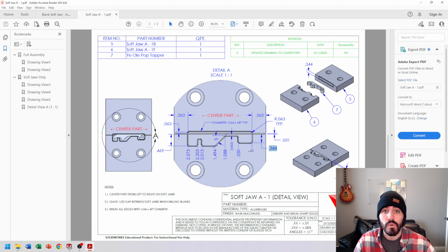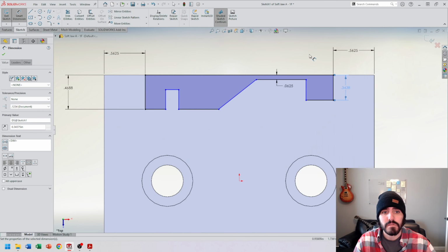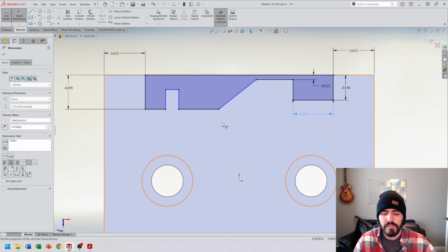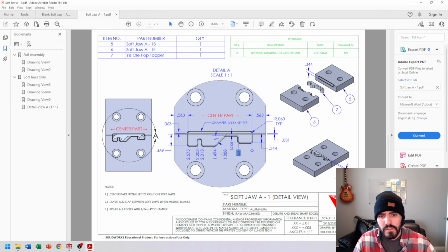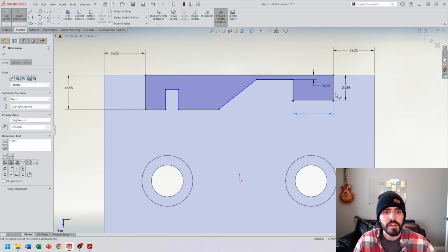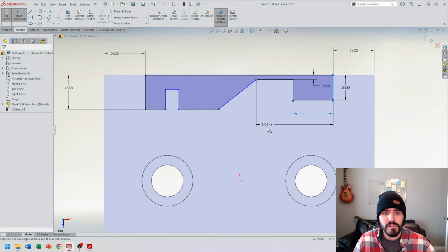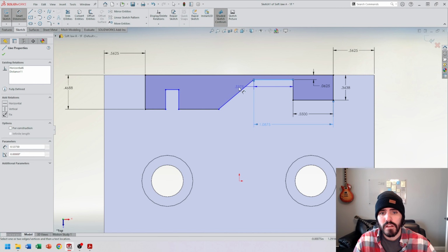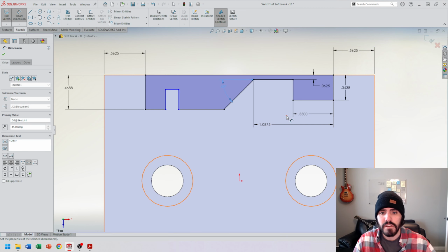So this is just like an ordinate dimensioning system. This is saying that this is 0. And then from this edge to this edge, it is 0.55, so 550 thousandths. So I'll go here to here, 0.55. This one is 1.08, and we'll just make it 1.0875. That degree I knew I saw before I went over was 45 degrees.